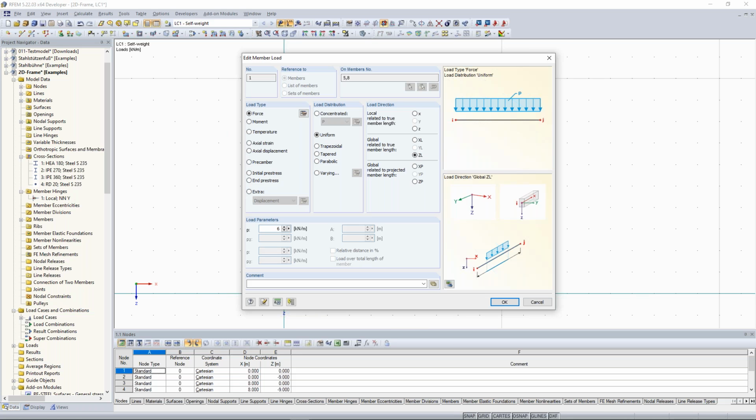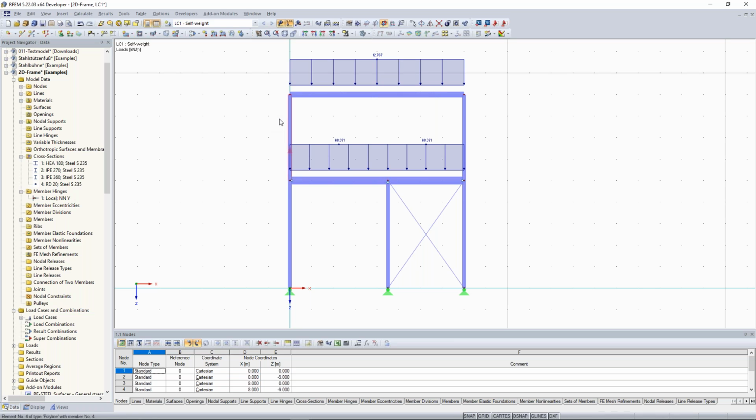And then I want to create horizontal forces, in this case in the global X direction. So I can choose here the members. I choose it like here. So I draw my selection window from the right to the left corner.